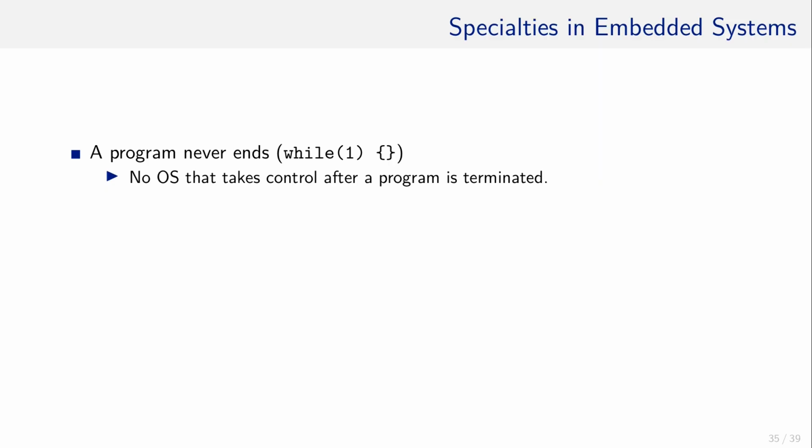Maybe it will execute instructions that are still there in the memory till it reaches the end of the memory and then restarts from the beginning. To prevent this undesired behavior of unknown states, the program always contains an endless loop, such as a while(1), which is always true.